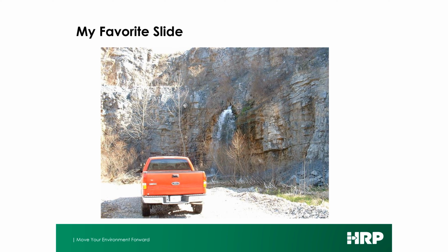And this is my favorite slide of all time. You may have noticed on that last slide that the groundwater contours, they're going towards the river, but they also seem to be peeking up towards the northeast there. I should have pointed that out, I apologize. Just to the east of this site is a limestone quarry. This is about 200 feet deep down in it. And what you're seeing in the wall there is actually a karst conduit flowing at many hundreds of gallons a minute, 24/7. And it's still flowing today, but it's underwater because the quarry flooded. I just love that shot, and I got to work it into every talk I do.